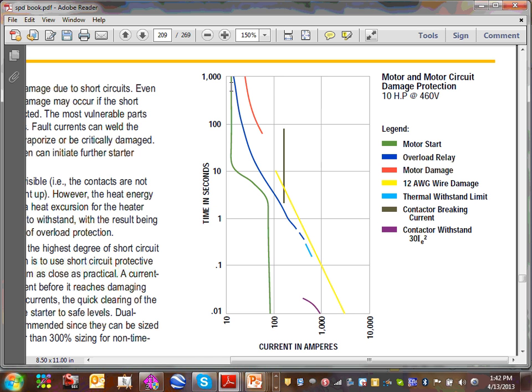That's then when you start it though, it pulls close to 90 amps. Can you guys see right at the bottom here? It pulls up. That's the starting up to almost 10 seconds. Then it goes back to normal. That's the starting curve on an induction motor, design B induction motor, typical, right? So that's what you need to protect the motor and allow it to start.